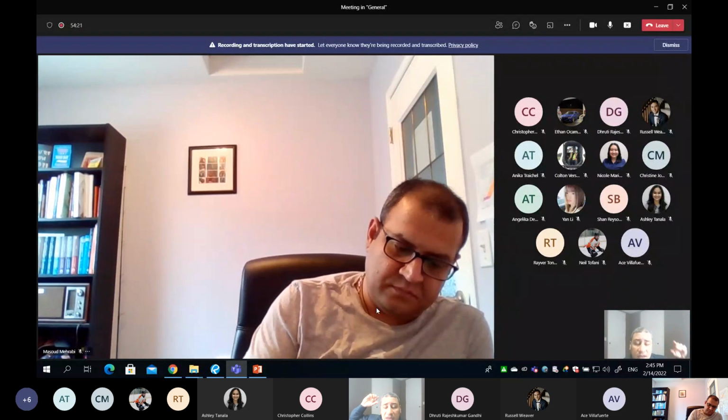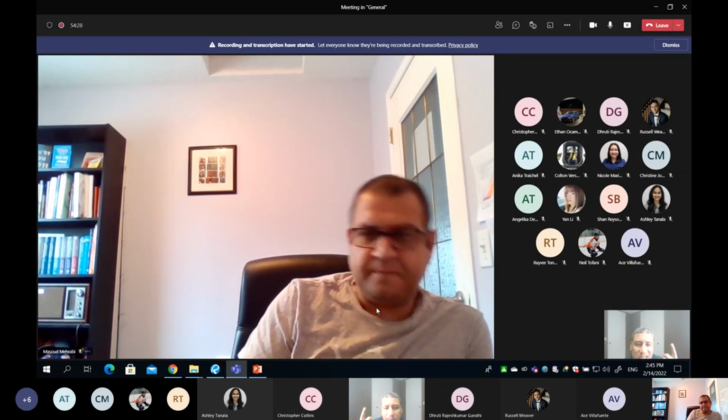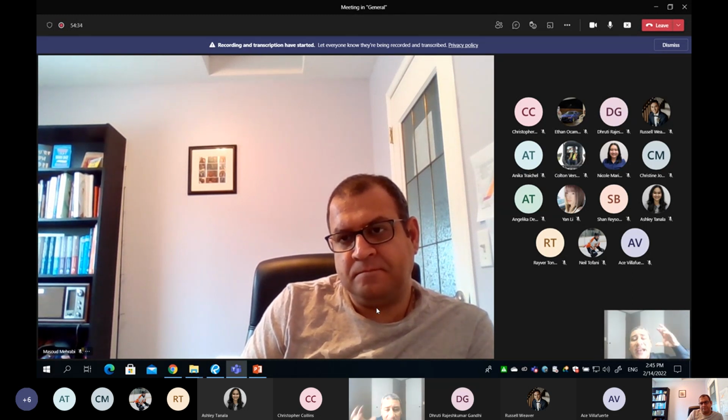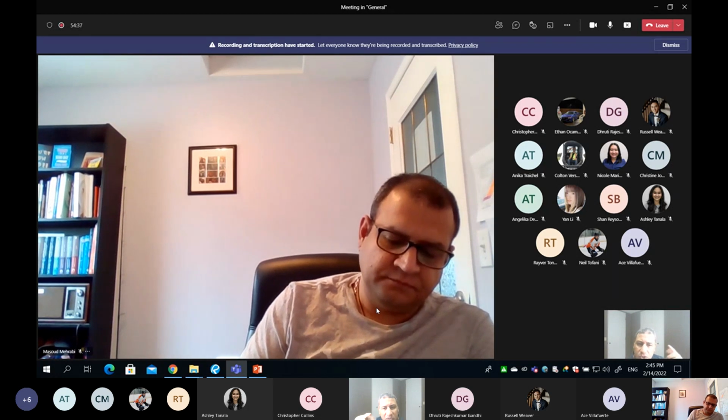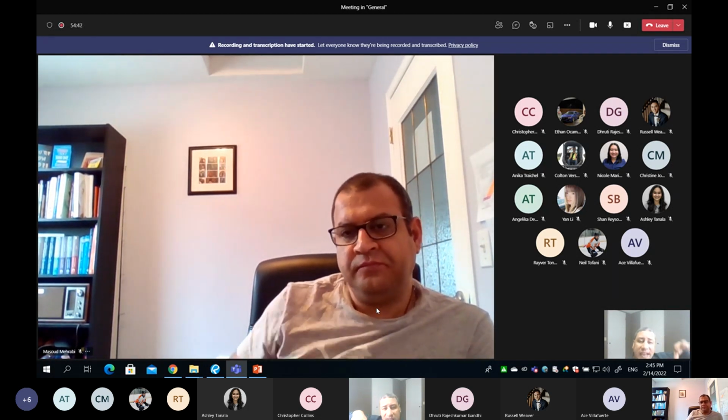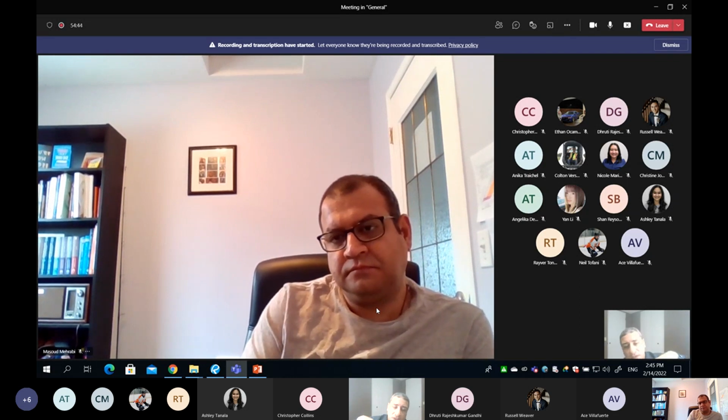While if this ratio is 100 or 150, it means your column is so slim that the failure of the column will not be because of material failure, it's because of the instability of the member. Do you get this idea? So the failure could be due to failure of the material or instability of the column.